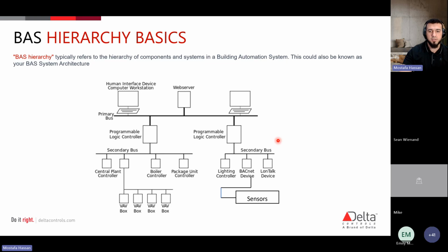Next up is your supervisory building control level. And these servers, these heavy controllers, right? They coordinate multiple controllers and systems. They may handle tasks like scheduling, alarm management, and data logging. And then as you go down, these are more application-specific controllers, but depending on the size, you may still need to use a more supervisory controller, depending on the manufacturer's product line.